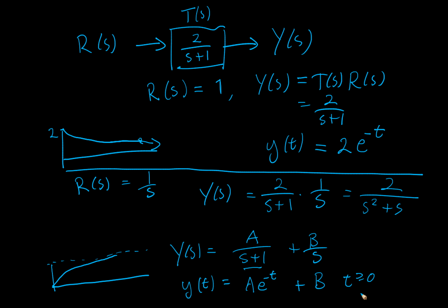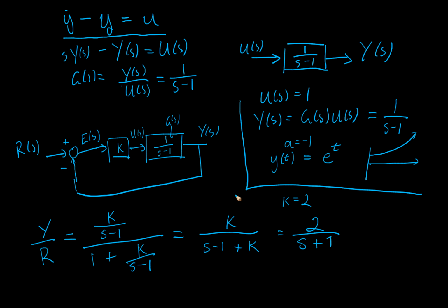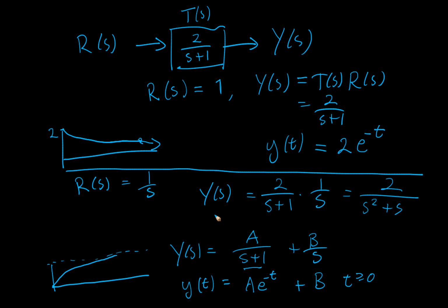So we've seen how converting a differential equation into an algebraic equation can help us understand the input-output response of a system. We've also seen a very simple example of how putting a system inside a feedback loop, measuring the output, computing the error from where you want it to be, and then multiplying that by a constant and putting that around, can actually stabilize an unstable system.